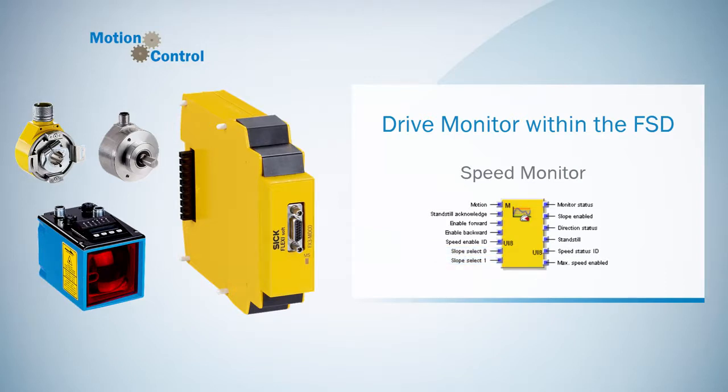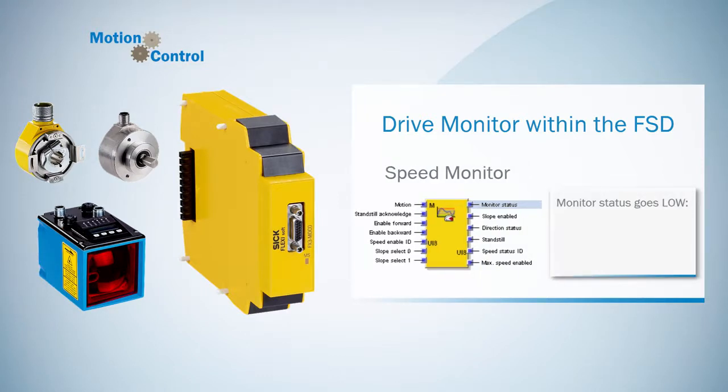Now, the outputs. The output monitor status is normally high. It goes low if one of the following monitoring functions has the result 0. Monitoring of the reduced speed selected via the input speed enable ID, monitoring of the maximum speed, and direction monitoring. The output slope enabled is high as long as the speed slope is active. To indicate the direction, there's the output direction status. 0 means forward and 1 means reverse.